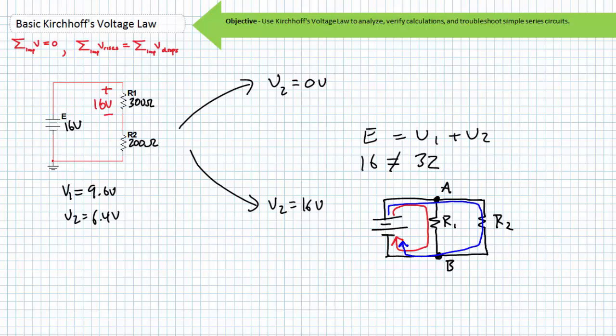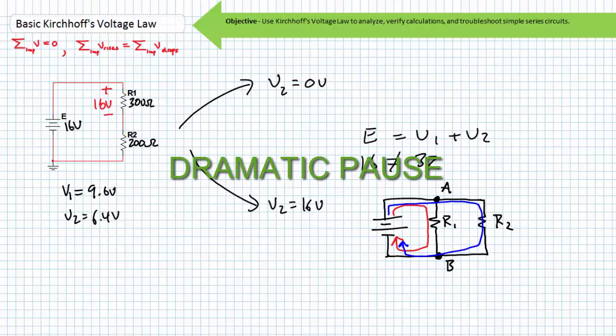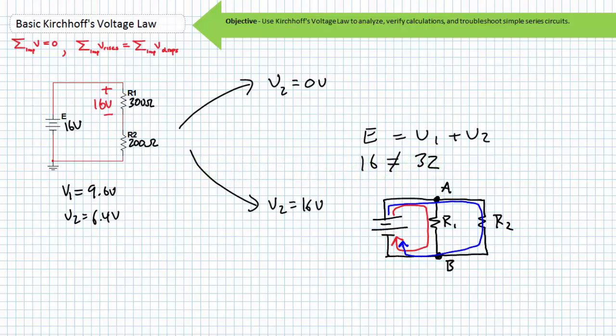This may not seem relevant now since we're dealing with primarily series circuits, but realize I just tricked you into learning the fundamental property of parallel circuits using a technique you should, by now, be intimately familiar with, notably KVL. Allow me to elucidate 2 very important electrical properties. Dramatic pause. Elements in series must carry the same current. Elements in parallel must have the same voltage across.